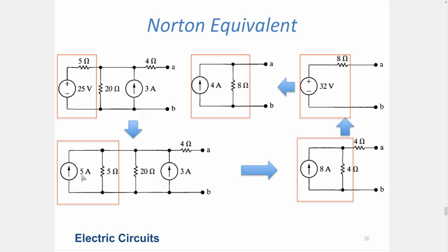Now, if you look at the circuit, our original circuit and this circuit are the same from a circuit theory point of view. They behave the same. Now, it's easy to write down the KCL equations or minimize this circuit. I can simplify it into a circuit like this, okay? And again, I can create another source transformation.